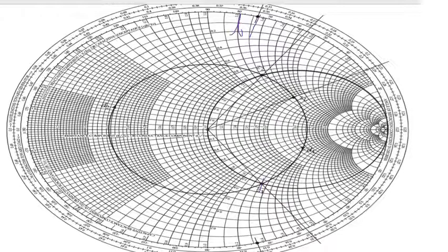The L2 point will be exactly similar, meaning you will find the Z2 point. There is your Z2 point. This is your Z2 point. The complex conjugate of this will be the Z1 point. Find it in terms of lambda, just take a straight line. Whatever value you get, that value is greater than 0.25 lambda. Subtract 0.25 lambda from it, and the remaining value will be your L2. Am I clear? So this is how you find out your design.